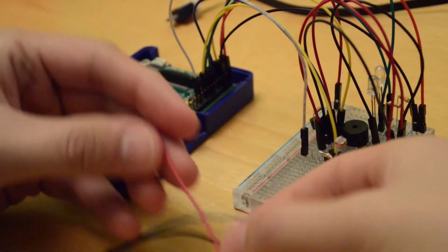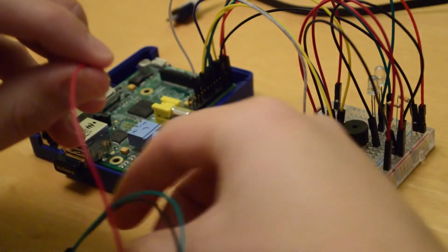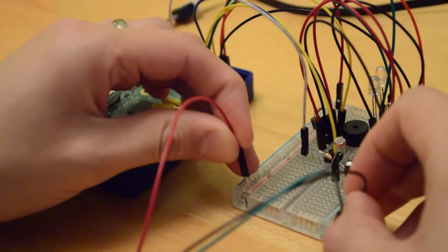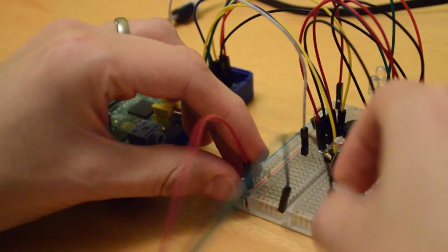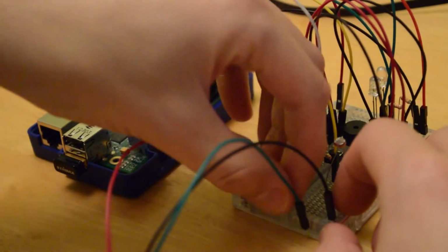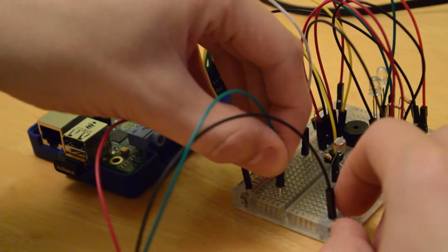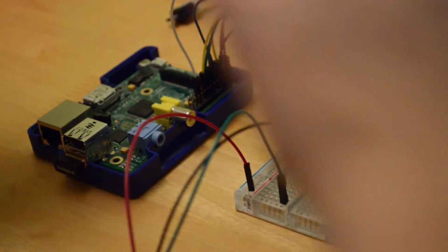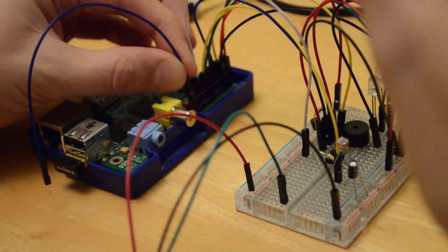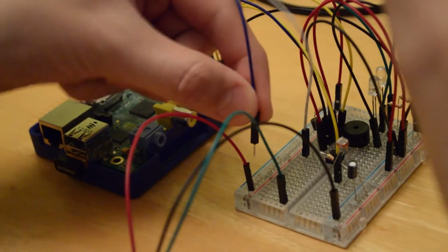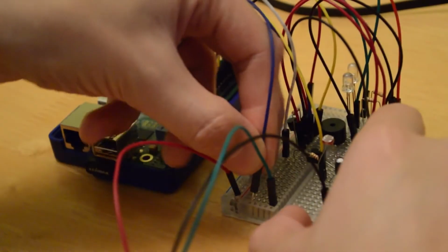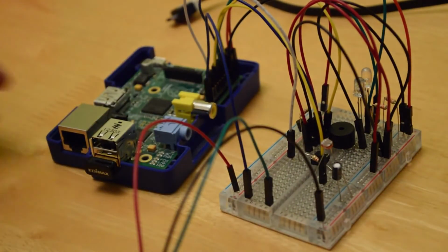Okay, here's our passive infrared sensor. So we're just going to connect up our voltage line to the new 5-volt rail. There it goes. Going to connect our ground to the ground, and we're just going to put our GPIO pin just anywhere, and then we're going to get a spare wire to connect up the two. So from our GPIO pin connecting up to the passive infrared sensor, and there we go.